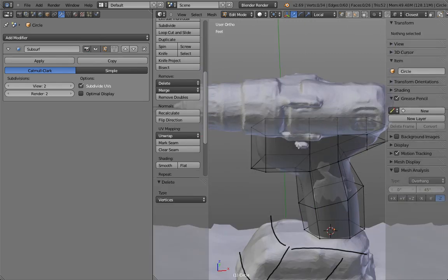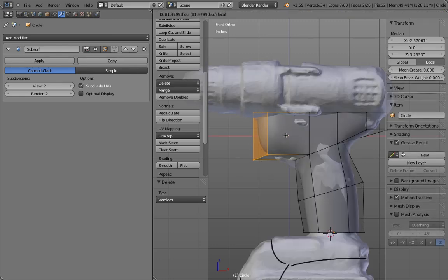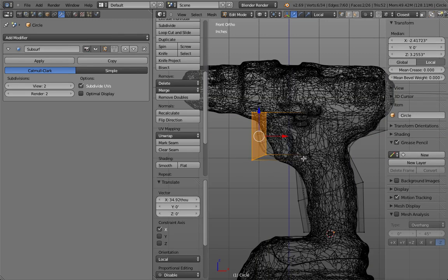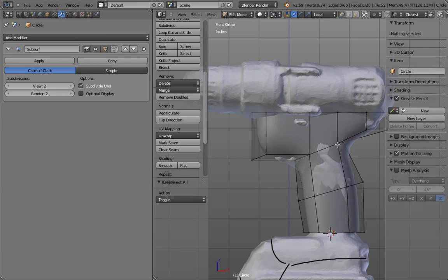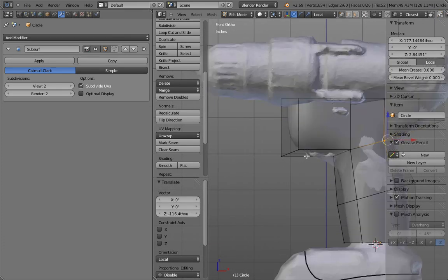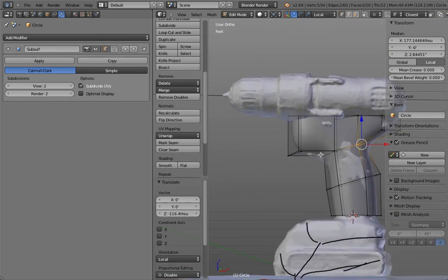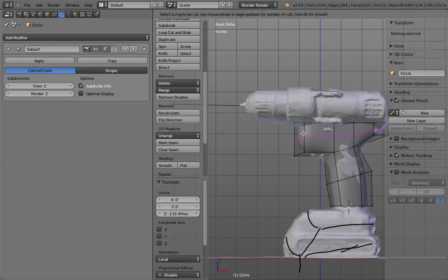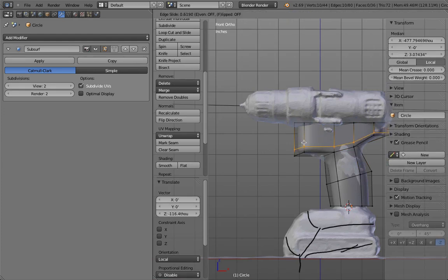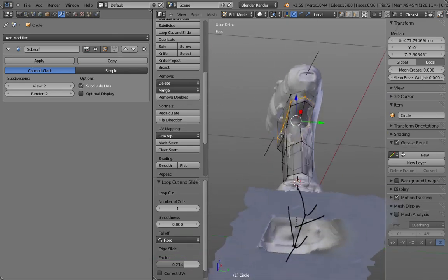There's this top face I have to delete. And then C. Yeah. And this is very round there. Maybe at that point I would like to add a loop cut and move this one down, so I can straighten the upper surface and then have a rounding.